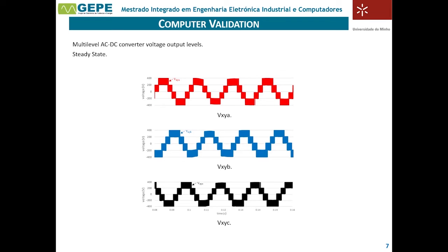This image presents the voltage output waveform of each of the converters that compose this three-phase system. It is possible to observe at 0.1 seconds the moment when the harmonic loads are connected, because the DC link sinks for a short moment and then recovers as the filter starts compensating. This validates the correct operation of the multi-level converter, since all the levels are correctly produced.